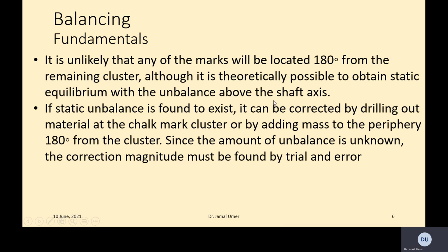Although it is theoretically possible to obtain static equilibrium with the unbalance above the shaft axis, which we will do in a couple of slides, the theoretical calculations. If static unbalance is found to exist, it can be corrected by drilling out. Now, this is the remedy. So you have the static unbalance, you have found it.